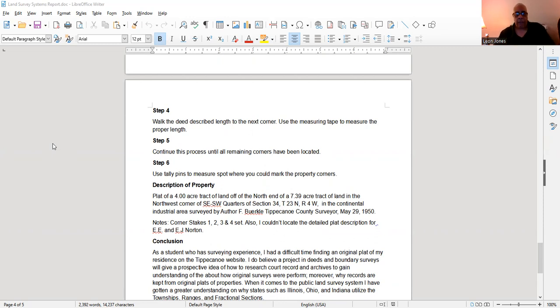What I have for my notes is that if I was out there, I would go ahead and set any points that have been broken or obliterated, and I would reference the existing points. And I would note them, because when you get the plat, you can also make copies of it for yourself.